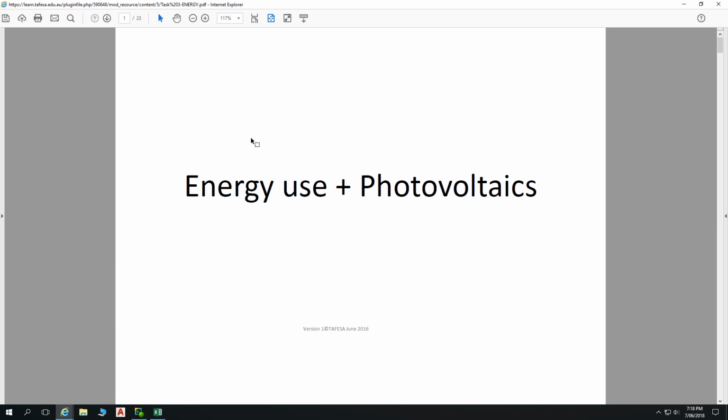Well, that comes from whatever you specify for your light. So if the 240 could turn into 320, 320 would just carry down anyway, wouldn't it? Yes. But we're using the same coefficient of loss, those two factors, to end up with the 0.48. Underneath anyhow, it's only the top factors in that equation which can change. So the lux you determine at the desktop, and the square meterage you work out is how many square meters you're lighting up in the building as well.